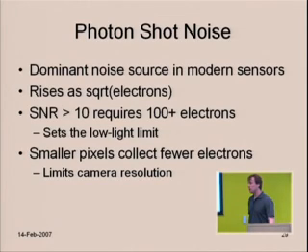Is there a significant difference between CCD and CMOS sensors when it comes to noise? No, not anymore. There used to be, and CMOS got a lot better. Recently the CMOS sensors are very slightly ahead, but I would imagine that doesn't have anything to do with CMOS versus CCD fundamentally, and I suspect it has more to do with the amount of money spent on trying to make CMOS sensors work versus CCD. This motivates the talk to come on sensor noise and how those statistics work.